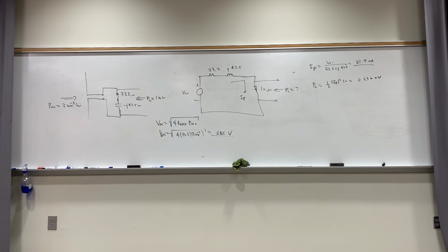If you hold the separation distance constant and I move them like this, there's zero field from this one getting into that one. And they're related by what? The angular function squared, right? Really, it would be the cosine of (pi over 2 cosine theta) over sine theta, where theta is measured from the z-axis, squared, times the other stuff, the j60 I over r.